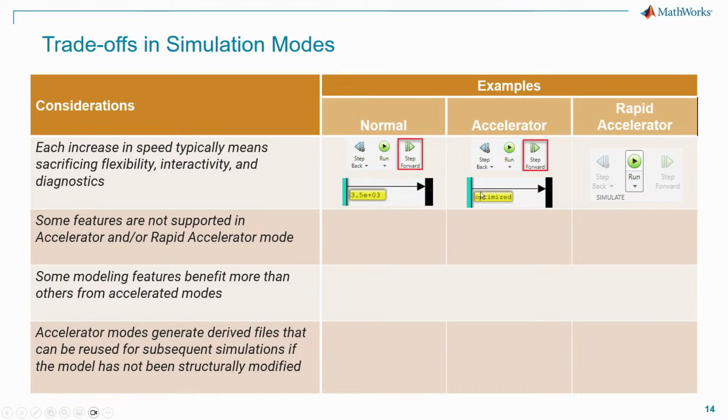In accelerator mode, you can do the same thing. You can step through the simulation, but you'll notice that some signals have been optimized away in favor of speed. And in rapid accelerator mode, we can't step at all because it's a totally separate process.